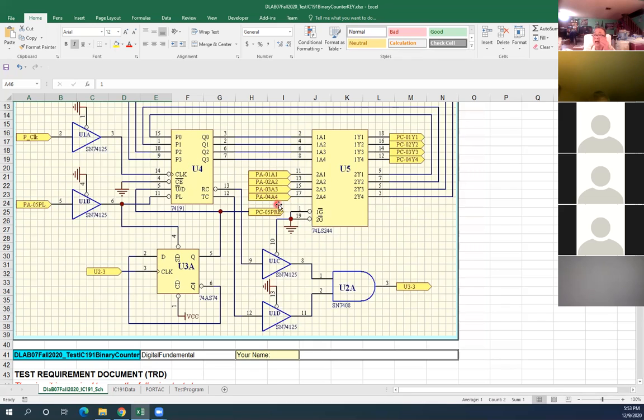That means you apply number 5 in the input here, it goes this way. Goes back to the P0, P1, P2, P3. And now you can read it out. It will be number 5. This test, if it fails, what caused the problem? It's the same. U1, U4, U5. Okay, U1, U4, U5. All the loads are like that.